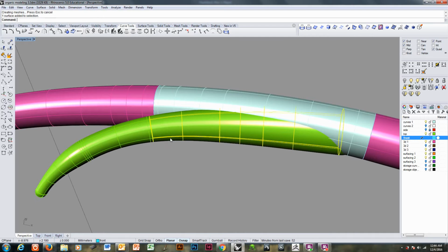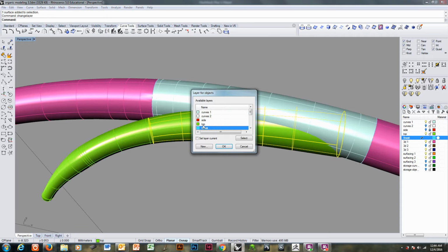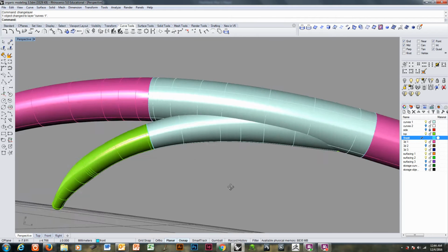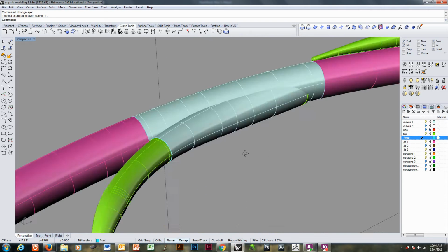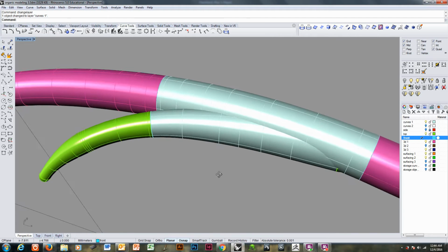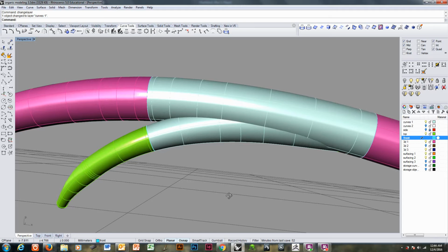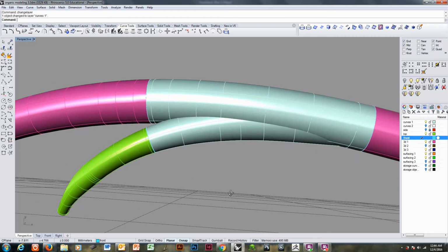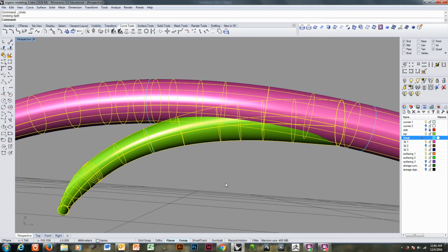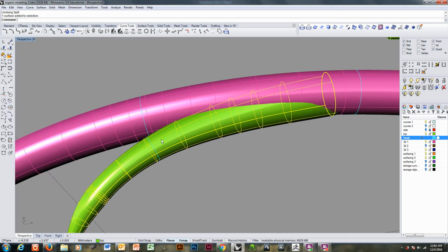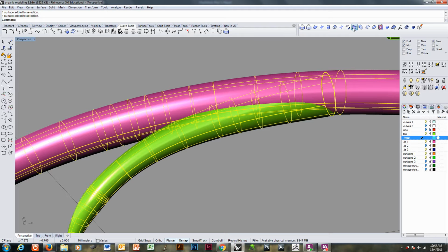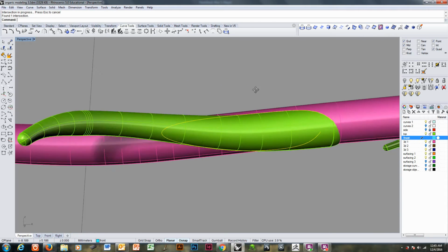This is what's called a Y seam in Rhino, a Y joint, and they're one of the worst things to try and handle in Rhino. That's why I'm taking this time to show you how it's done. There are a couple of approaches. Actually, I'm going to pick a simpler one than this. You guys have enough on your plate right now. So, rather than using these curves, I'm going to use an intersection curve between these two. Okay.